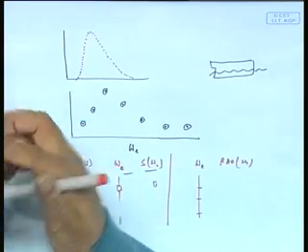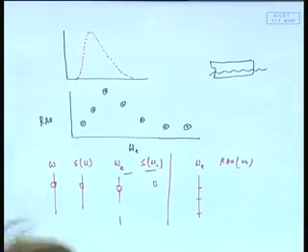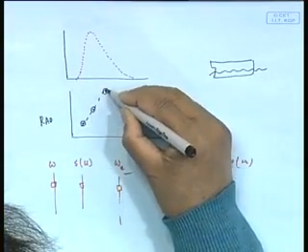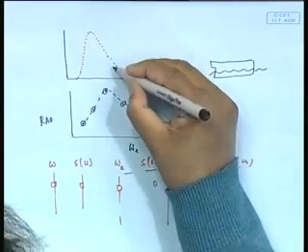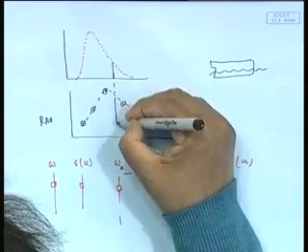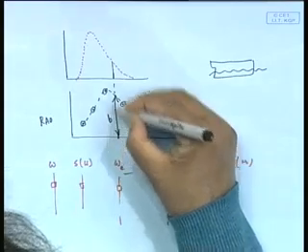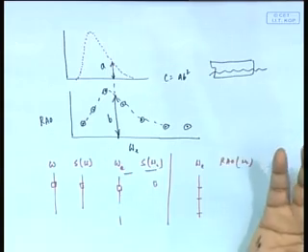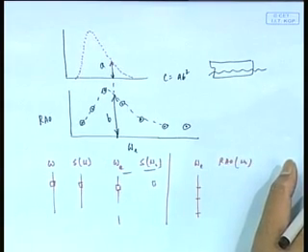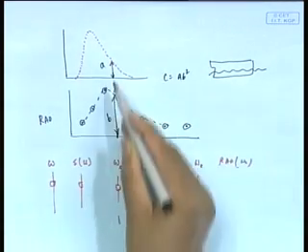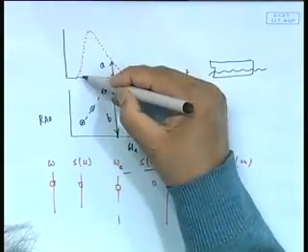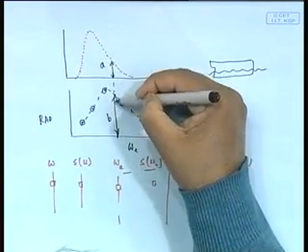So you have to make sure that you do proper interpolation, because see here, if I draw this graph, I have to choose this value as B and this value as A, to get C equal to A B square. So I require an interpolation in some sense. I cannot simply take it, because this A equal to B square is for that given omega E. So I can choose some discrete values here, and for those omega E's I find out what is my this, and what is my this.